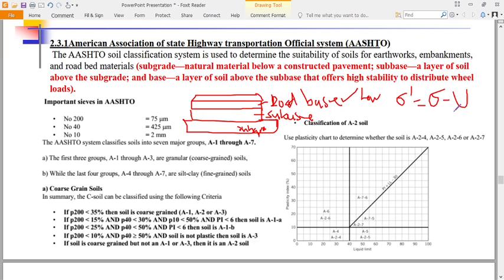So the higher the amount of water, the more the ability of the material to carry load reduces. Since this is a layer nearing the wearing course, it should be a layer with higher ability to dissipate or carry loading.